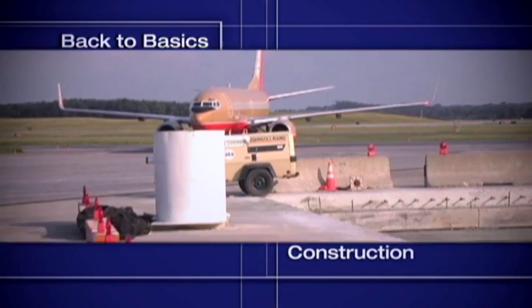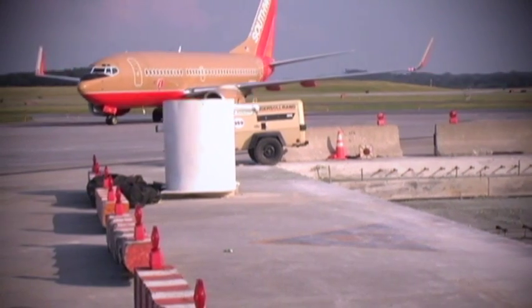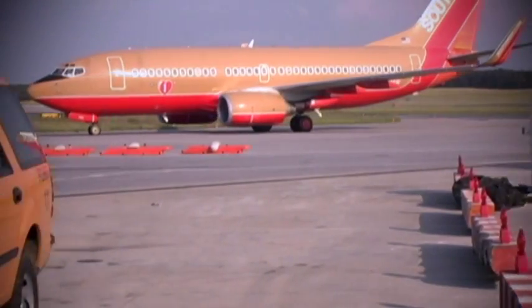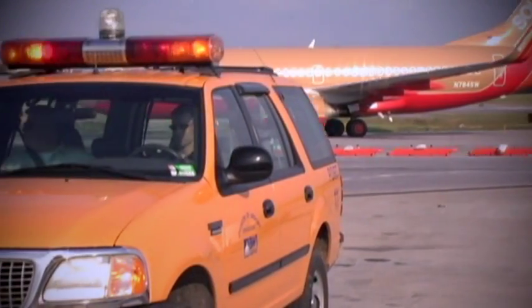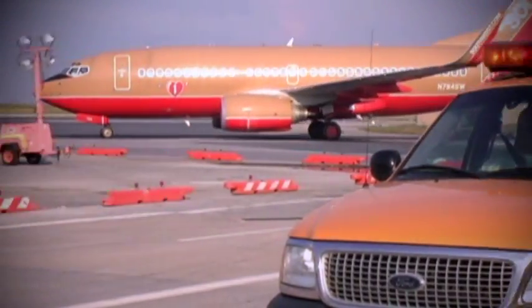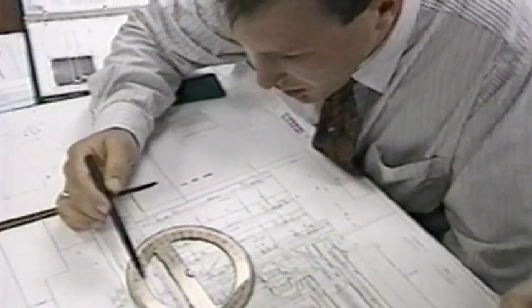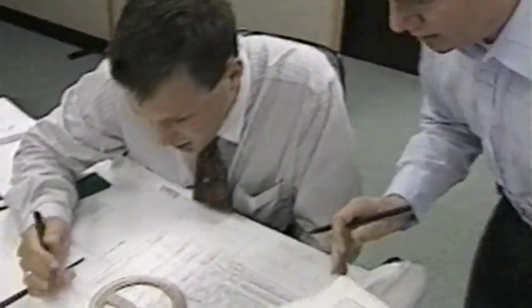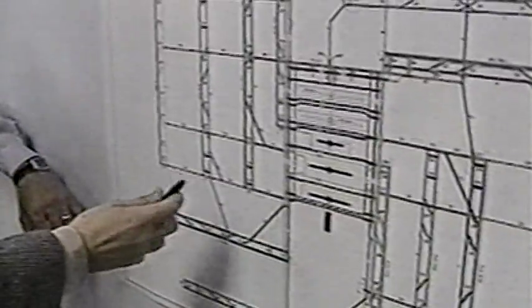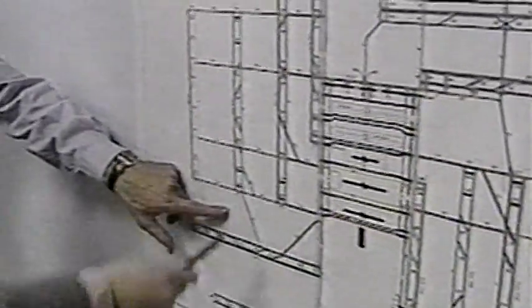Safe aircraft operation can be affected by construction activity. When there is construction at your airport, the daily inspection should focus on it to be sure that a high level of safety is maintained. Continuous surveillance are the watchwords. Any construction project should have a safety plan as part of its plans and specifications, and the airport inspector should become intimately familiar with it even before work begins.